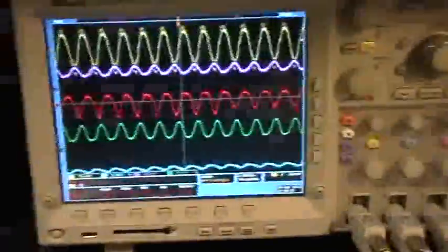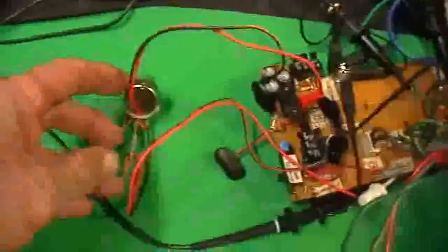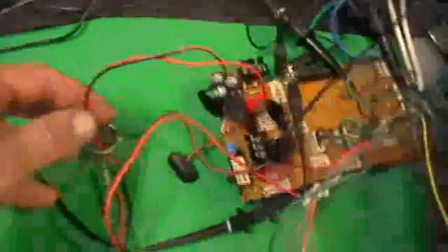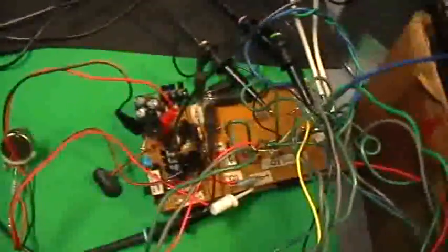Okay? So once again, we're running off of the main battery only through the charge pump inverter, which is supplying a negative bias signal to the function generator plus input through the potentiometer and the 10R dropping resistor, not using the 50R in there. All scope probe leads are grounded at the board. All probes are taken at the board. There's no need to add any wire or move the probe leads around or anything. This is all just done by the addition of decoupling caps.